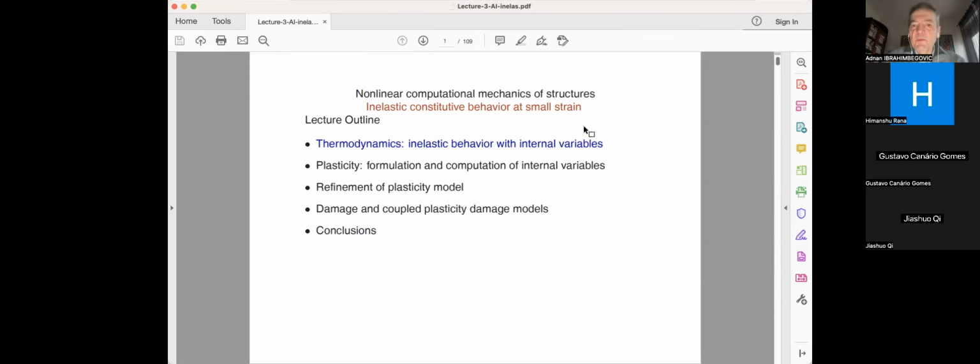for the inelastic behavior. And in particular, in order to complete the full picture, the other thing that we need is so-called internal variables. I'll talk about that in a moment. These are something like a plastic strain, let's say damage compliance, hardening variables, and so on and so forth. Then I will take plasticity to start with and show you in a 1D problem, we go back to the first lecture, how you actually carry out computation when you have plasticity.